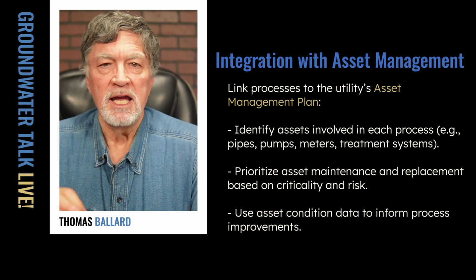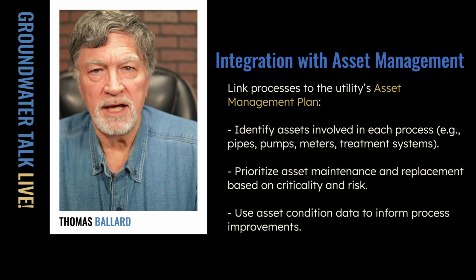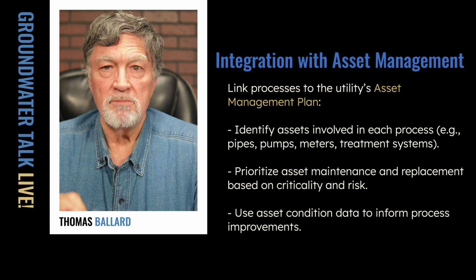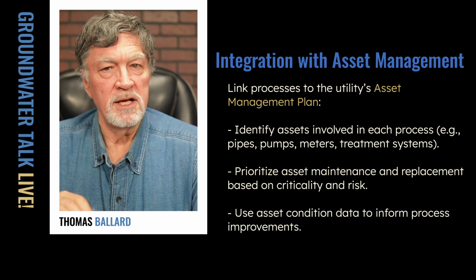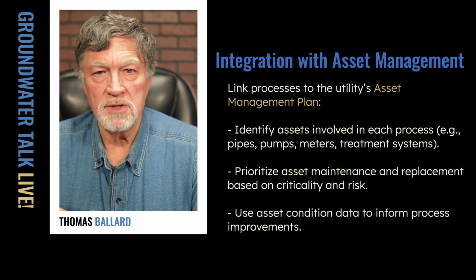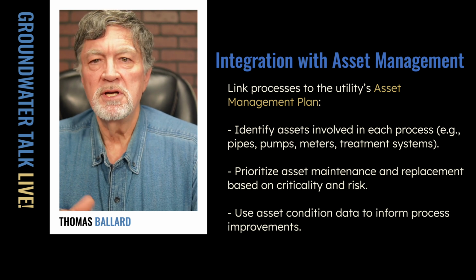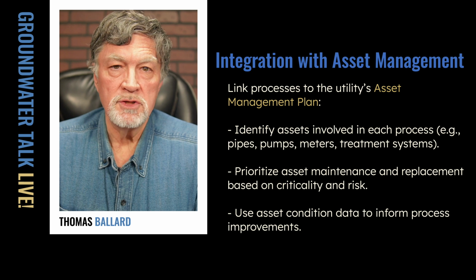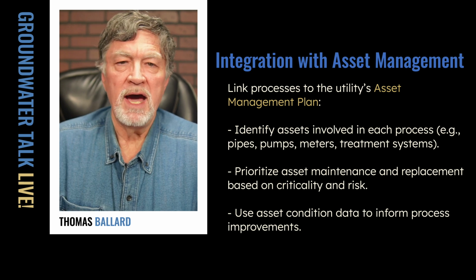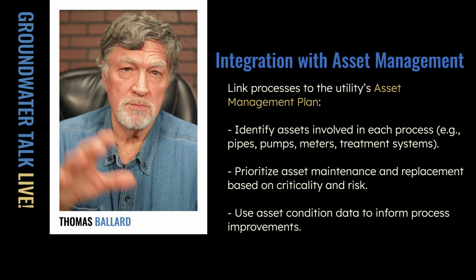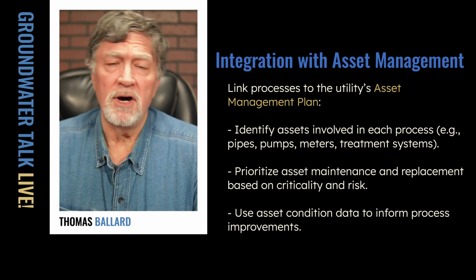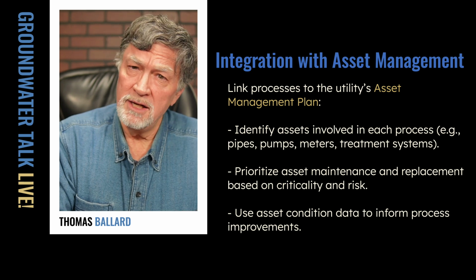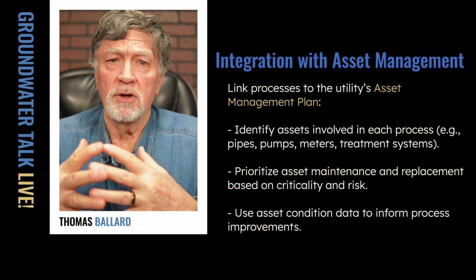All right. Integration with your asset management plan. You need to link your processes to the utility's asset management plan. So we want to identify assets involved in each process. So the pipes, the pumps, the meters, the treatment systems, whatever, that goes into your asset management plan, that those that are involved in this particular process need to be identified and integrated there, because criticality of assets versus criticality of the specific process, they're going to work together.